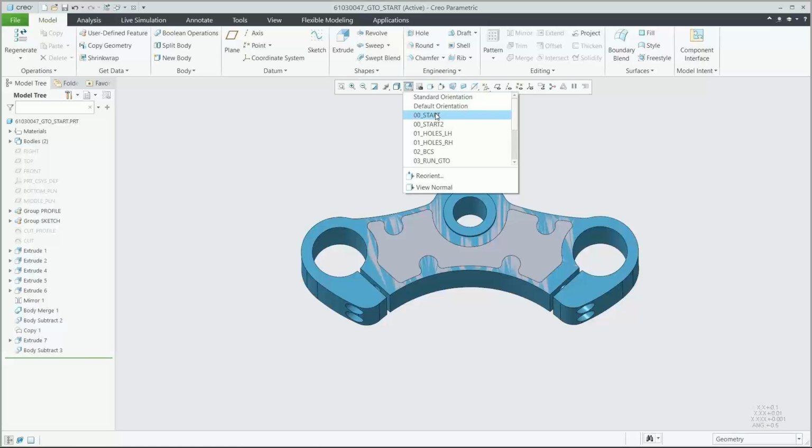And with that, we can simply go up into our applications and click on Generative Design to get going. So again, not even another window or different software we have to hop into, same exact interface to go through and start to work with our generative design study. Now, first thing we'll do is click our starting geometry, which again is going to be that overall envelope, and do the same thing with our preserved geometry. Just make sure that's going to be included in the final design.